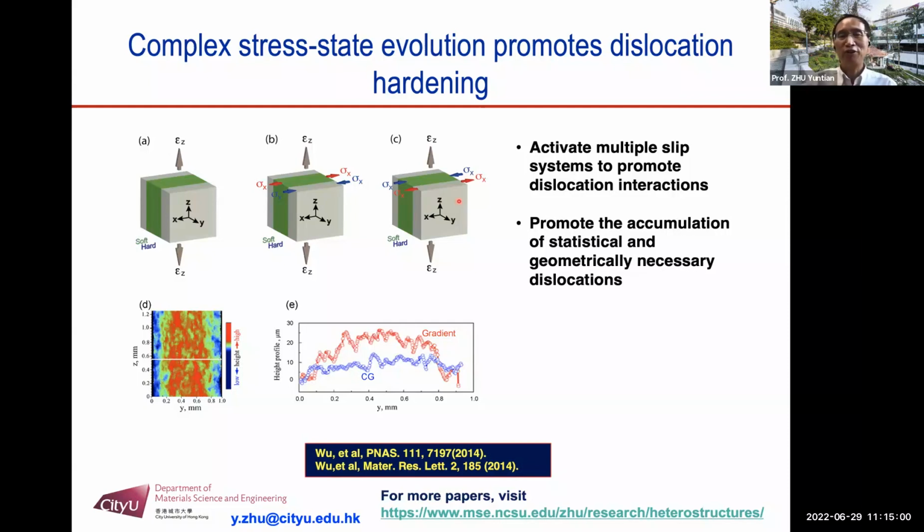It's not stable plastically. It will start necking first. Then that's when the surface layer will shrink faster than the center layer. The center layer becomes more stable. As a result, the surface will shrink more.